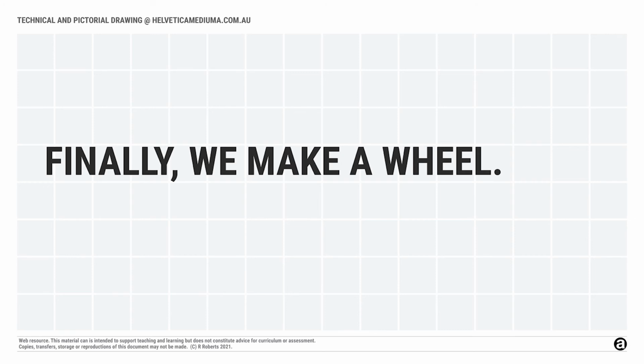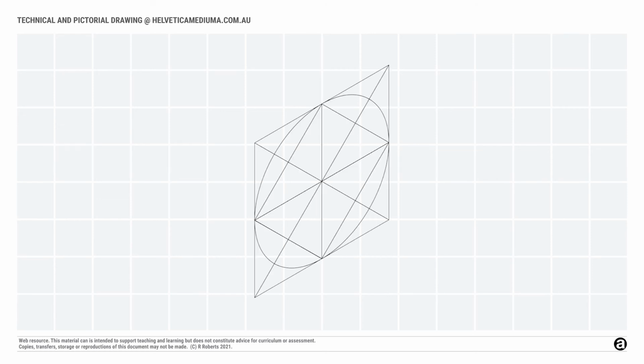Finally, let's use this knowledge to make a wheel using isometric ellipses. The first step is to draw your first ellipse using the same method that I've described. The next step is to use isometric lines to extend outwards from that first ellipse the thickness of the wheel that you need.